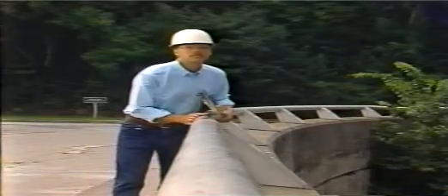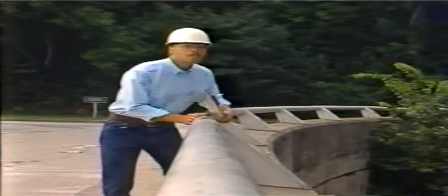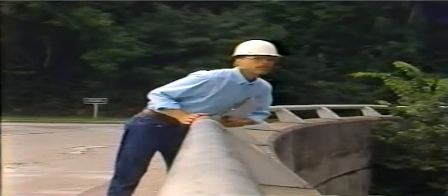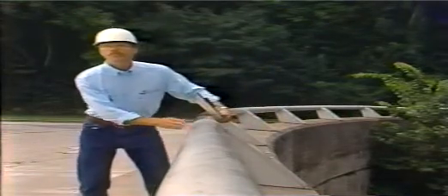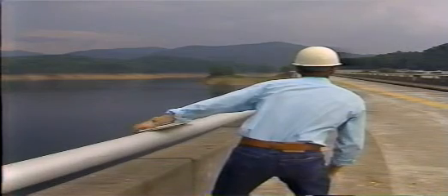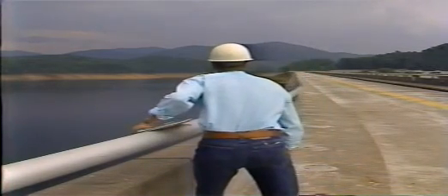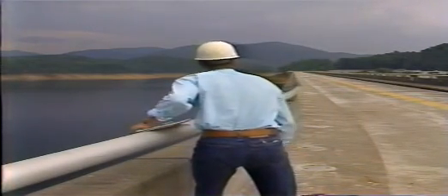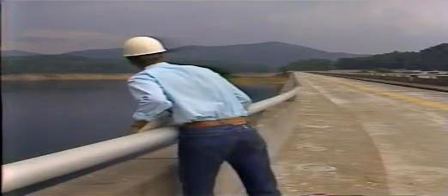Sometimes displacement at a dam that has a straight axis can be detected by sighting along the crest and looking at the structure from several different perspectives. You can sight along parapet walls, crane rails, or handrails for indications of displacement. Another indication of displacement is cracks in the concrete around handrails and other embedded metalwork.